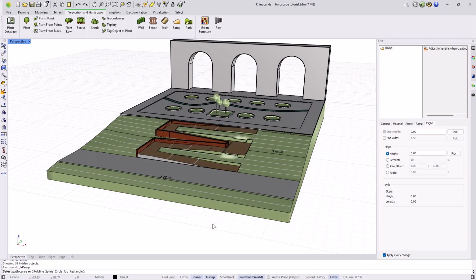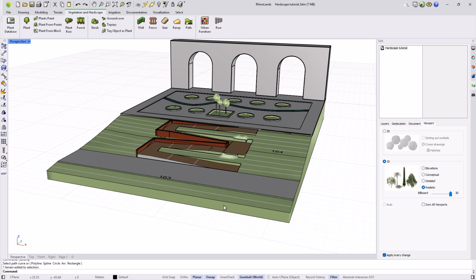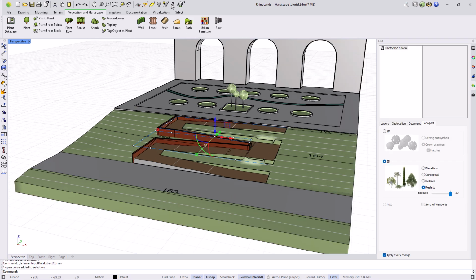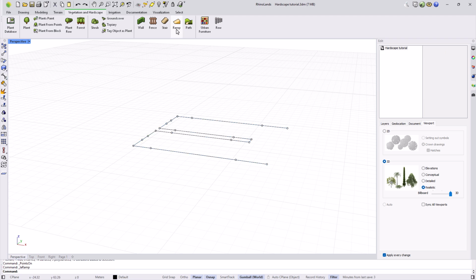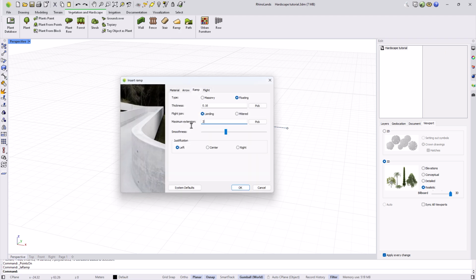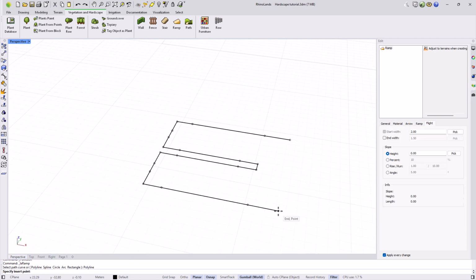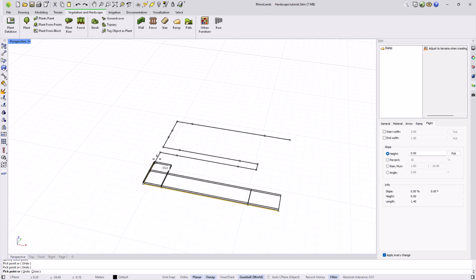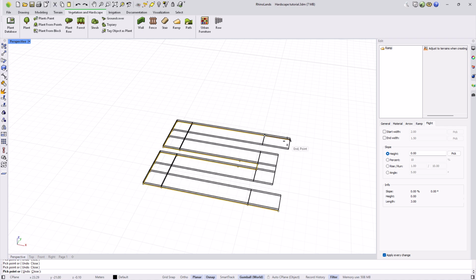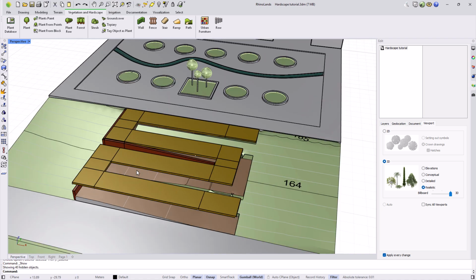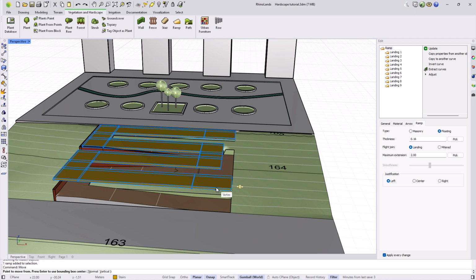Before creating this ramp, I will cancel the command to extract the path curve again, as it will serve as a guide. I reconfigure the ramp with the polyline option. I am going to redo the curve we used for the path operation on the terrain, but this time, without the vertices we created to make the landings. Once generated, I move it to align with the height of the terrain.